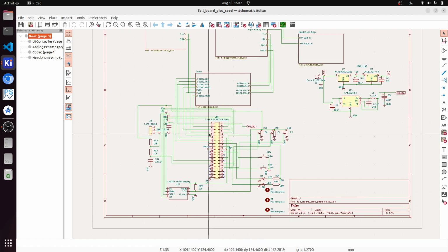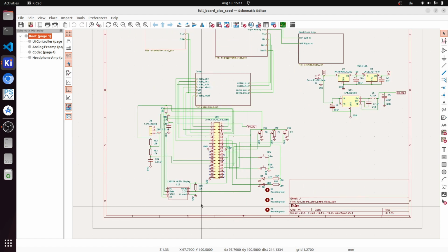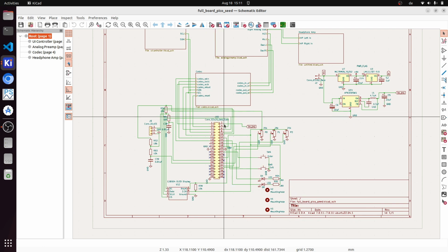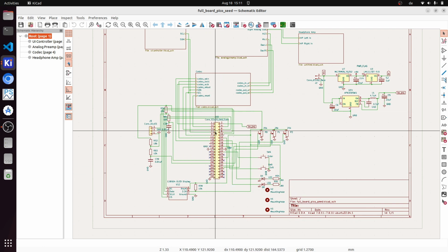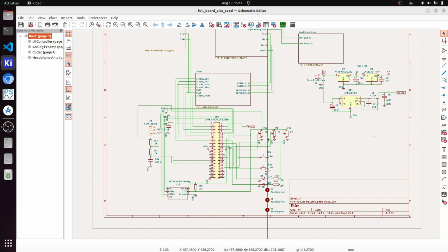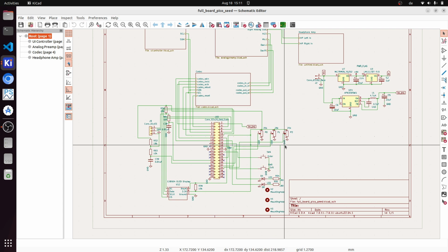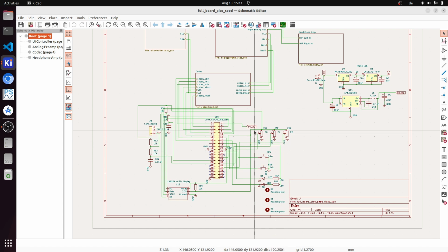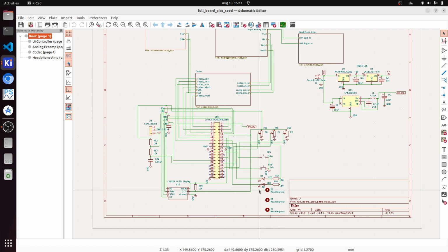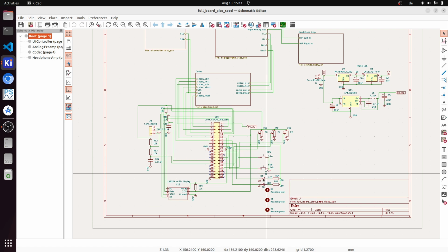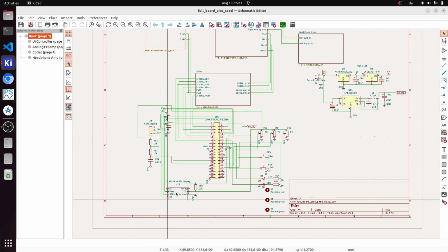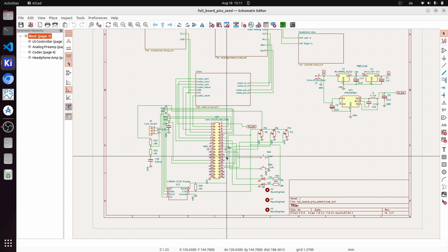So let's start with having a look at the schematic. I start at the center, so to say. This 40-pin connector connects to either a Raspberry Pi Pico board or an Electrosmith Daisy Seed board. And around the center are also all the peripherals, or all the controls, which are directly connected to the microcontroller board, such as the 3 potentiometers here, the clipping LEDs here, enter and exit switch, the encoder, and the display.